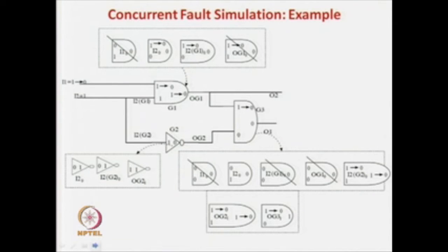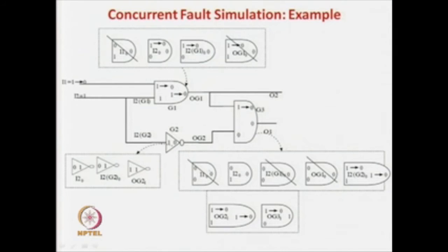What we have discussed is that now we have to see the benefits. Unnecessarily we were carrying some additional gates, gates which could not detect any fault. We were carrying those gates with us. But in deductive fault simulation, those gates were not being carried. So what is the advantage that you have to illustrate? If you just see, this gate, this gate, this gate were unnecessarily being carried because the output was 0 and this output is also 0.